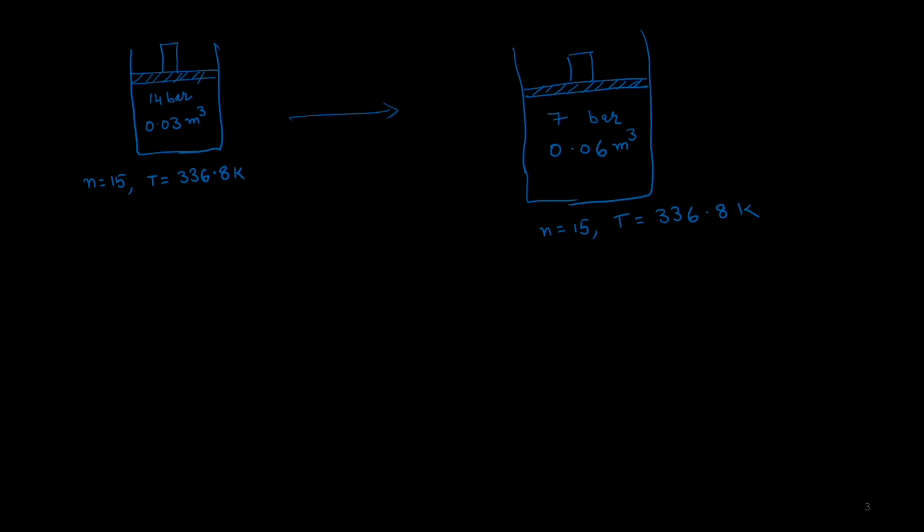Now, this is an isothermal process for an ideal gas. As we have done earlier in the previous lectures, delta U is going to be 0 because this is an ideal gas and there is no temperature change. Q is going to be minus W, which is the integral of P dV, and that turns out to be 29,112 joules. If you run through the calculations the way we did it the last time, essentially P is RT by V. Temperature is constant, so it will be RT ln V2 over V1, and then we can get the final number.